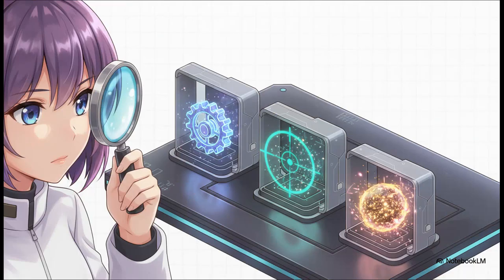And this brilliantly illustrates just how specialized these little units are. A processor relies on several very specific registers to function. You've got your instruction register, which holds the exact instruction that's currently being executed. Then there's the program counter, which keeps track of the memory address for the very next instruction the system needs to fetch, and the accumulator, which holds your temporary operands and the results of arithmetic and logic operations. They are incredibly fast for sure, but they only provide a tiny fraction of the memory you need.